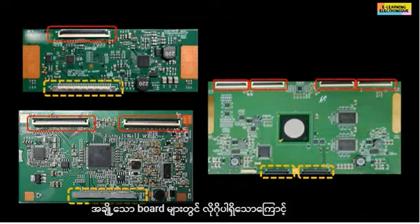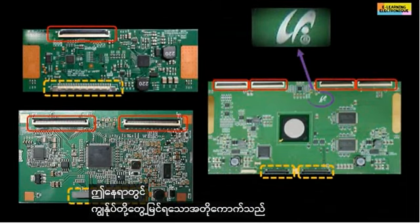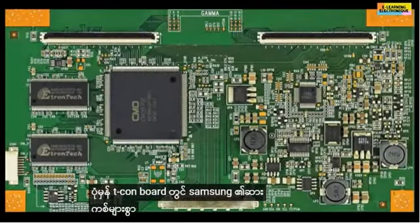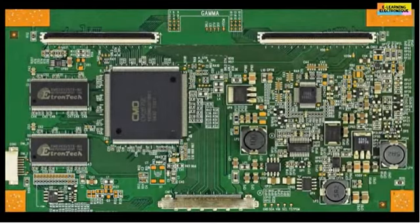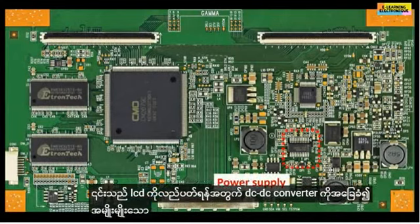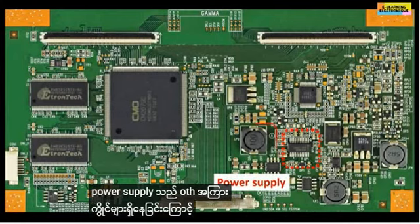Some boards have a logo. This makes it possible to identify the manufacturer, as in this example, where the acronym that we see here is that of Samsung. In a typical T-Con board there are several circuits. The T-Con board receives a single voltage for its operation. From this voltage, it will produce several other voltages thanks to a mini power supply. This is based on a DC-DC converter. Various voltages are needed to operate the LCD. The power supply is recognizable thanks to the presence of coils.